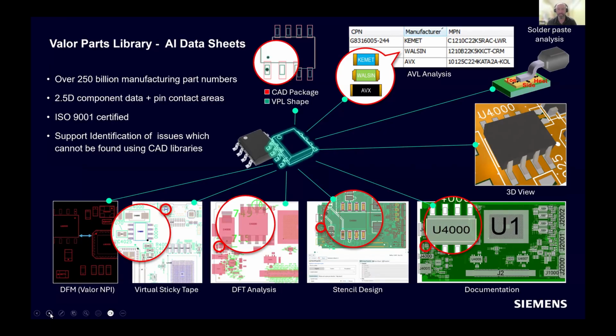So we have downloaded the datasheet for you. We have looked at the datasheet and we have captured all of the geometric properties: the component size, the height, the shape, the pin location, pin width, and all of that, and the pin 1 location. So if we have an MPN, something that you can stick in DigiKey and find, no internal part numbers or customer part numbers.